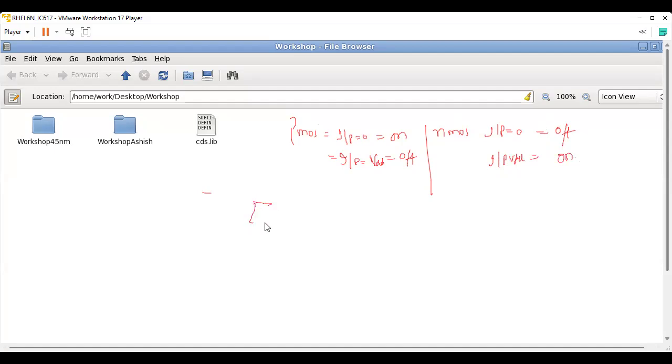It means that in a circuit, if PMOS is there, if we have 0 on the input of PMOS, 0 on the input of PMOS will turn it on. Means between these points A and B, PMOS will work as short circuit.